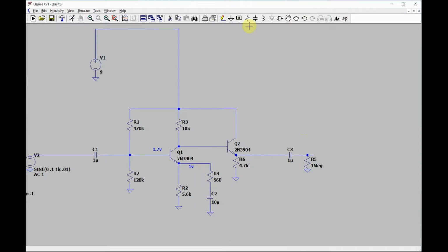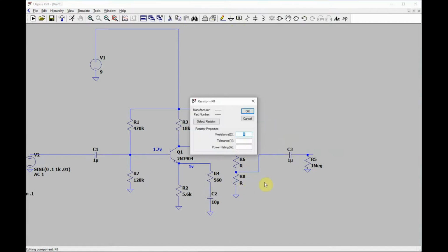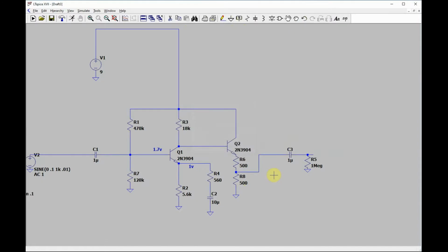As I mentioned before, this is another trick I occasionally do with amps to save a stage, especially if you don't know what the output needs to be. You can put a pot here, say a 1K pot, and if you turn it halfway down, you cut the signal down.